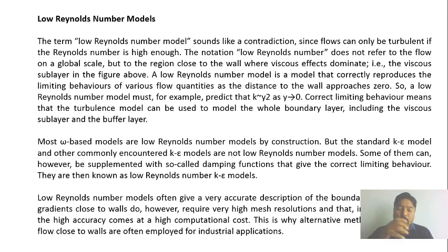How can we capture those different variations in the fluid flow region in different layers, from laminar viscous sublayers to buffer layers to the turbulent region? For that we need to develop a model which can capture all these variations of velocity, or you can say pressure and all these things. For that purpose we have developed these turbulence models. Okay, so low Reynolds number is not successful at capturing all these layers in a boundary flow. It will not give you systematic or good results for that particular problem. That's why the scientists and researchers developed the turbulence models.